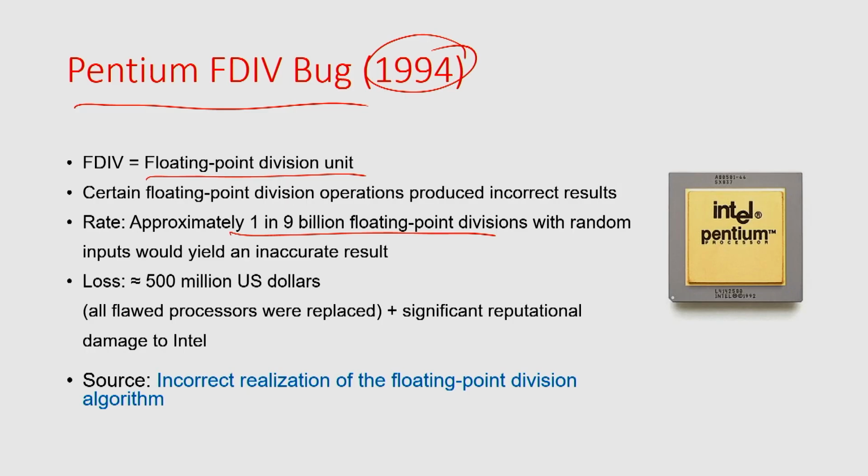So when you divide two floating point values, the value will be correct, but maybe after 4 or 5 digits there will be some mismatch, right. So it is not exactly correct, but there is some mismatch in the very lower precision bits, right. And that also does not commonly occur. If you do division in the floating point unit of this processor, approximately 1 in 9 billion operations it will occur once, right. It's a very hard bug to detect, right.